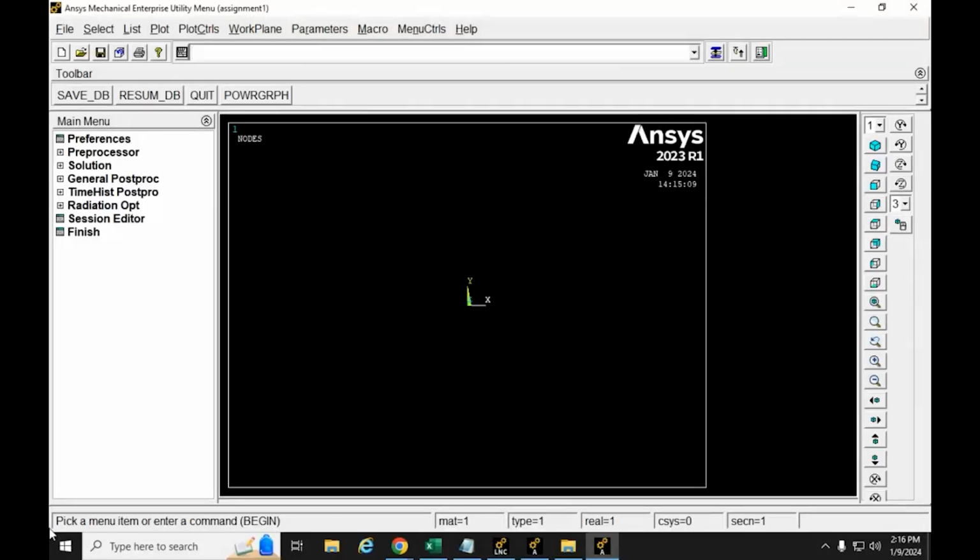They'll run the software still. But most of the analysis is being done in Workbench and the newer software Discovery. And again, Workbench, we'll get to in a couple weeks, is basically set up for importing solid geometries. So geometries you build in SolidWorks, Fusion 360, Siemens NX, you can export and import into Workbench.